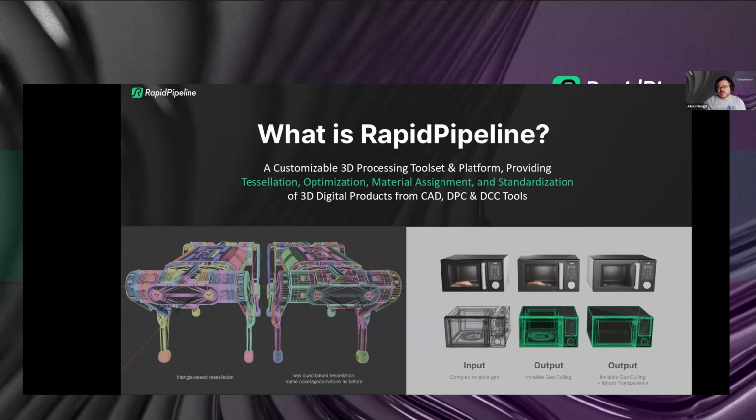And since almost 2 years now, we are also very much involved in CAD processing and how to get basically parametric 3D data inside the tooling. So that's a very different approach from just working on a tessellated, working on a kind of 3D model type of thing with triangles and quads and so on. The whole CAD ingestion is a complete new world where you basically have to convert the freeform shapes basically and solids into actual triangulated data via tessellation.